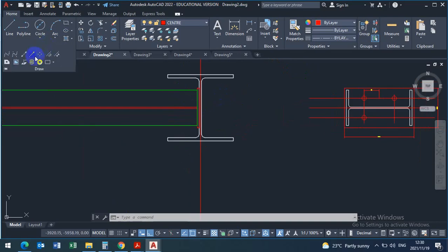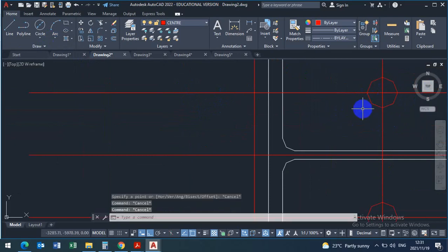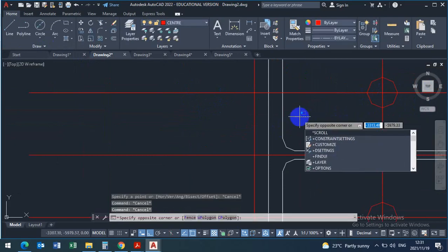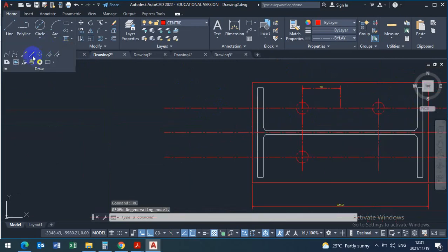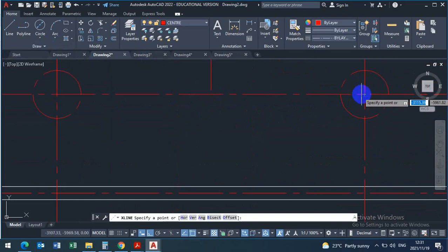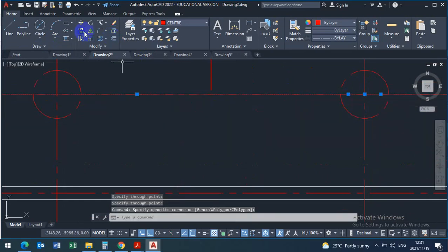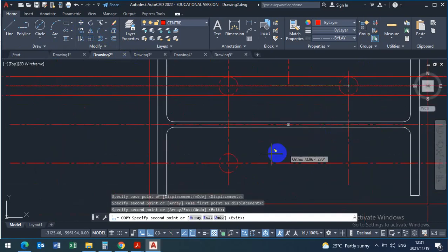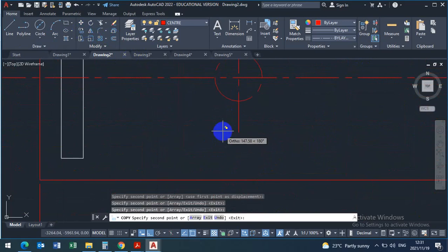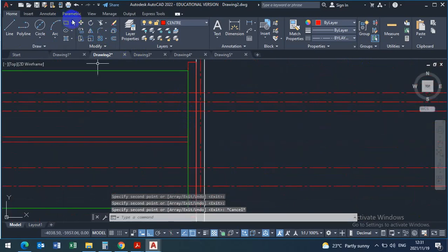I am now going to project the holes. RE, enter. Okay, when you see the circles like this, type RE, enter. Escape, RE, enter. Yeah, and then you draw your construction line and the center line also. There is the center line. Copy to here, and then that's the circle, both holes here and there. Okay, that's where the position of the holes will be seen.